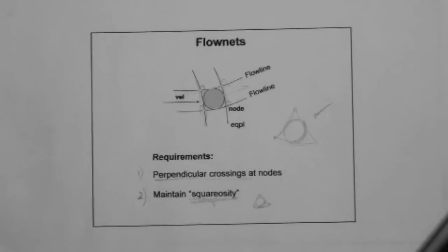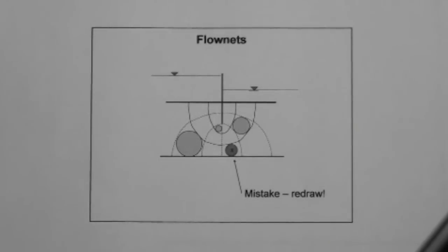Okay? Now, this is something very important, what I'm going to say now. Drawing the flow net correctly is essentially solving Laplace's equation correctly. Okay? So when you draw the flow net in a correct manner, then you have essentially solved Laplace's equation graphically. Okay? That's a very, very powerful tool the flow nets are, because they are a solution to Laplace's equation. So let's see how this applies to our flow net, the one that we were analyzing before.